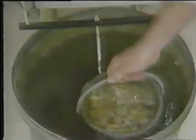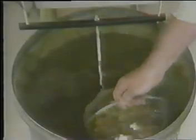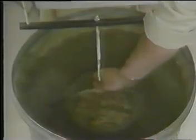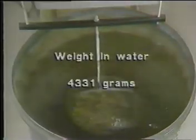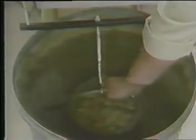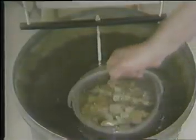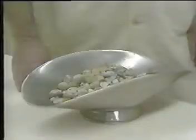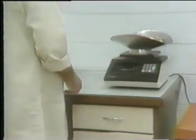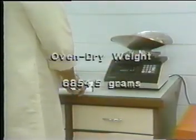Shake the submerged container to remove all entrapped air before weighing. With the scale or balance adjusted to compensate for the immersed weight of the container, the test sample weighs 4,331 grams in water. Remove the test sample from the water tank and dry it to constant weight at a temperature of 230 degrees Fahrenheit plus or minus 9 degrees. Let the dried test sample cool in air at room temperature 1 to 3 hours or until it is comfortable to handle.